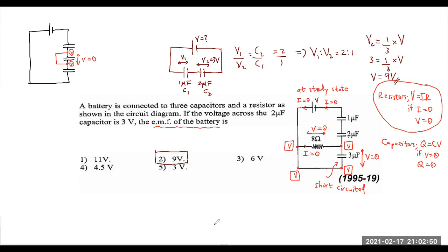9 volts. Okay. Now you will get the same result even if you have put just a wire without the resistor. I mean, if you have a system like this, still you are going to get the same answer because when you put a wire, you are short circuiting this. Now you must be asking, okay, there's a resistor here now.